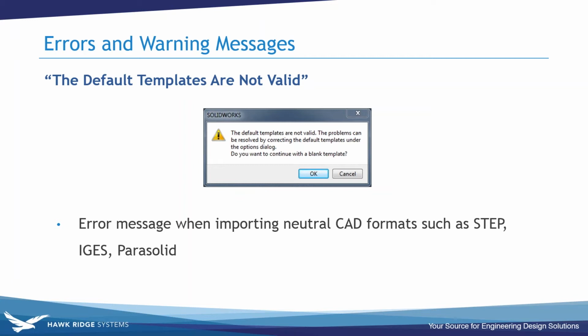So what SOLIDWORKS does when it imports a neutral CAD format is it automatically checks those default templates and uses those to open up the files. So if you do encounter this error message, it's important to just reassociate those default templates or just try a different template as well. And to do that, if you have SOLIDWORKS open here,